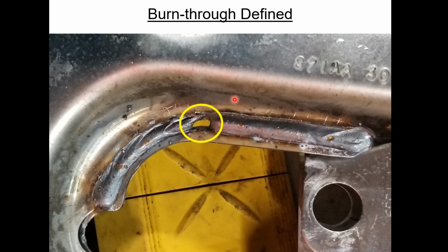Here's another good example. This is a part that can be repaired. There was an opportunity here to fix this small hole where they've had some burn through. In this particular case, this company had opted to put a small piece of copper behind the weld. Now, there's an idea, and it seems like a great way: put a piece of copper down behind, and then try to weld from the top side. Here's the problem. There's going to be some junk hanging down on the other side, and it's going to have a grinder put to it.